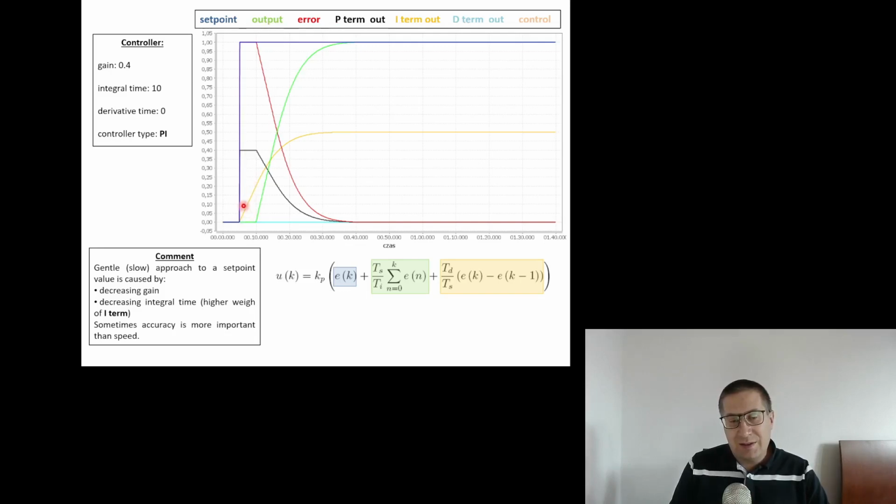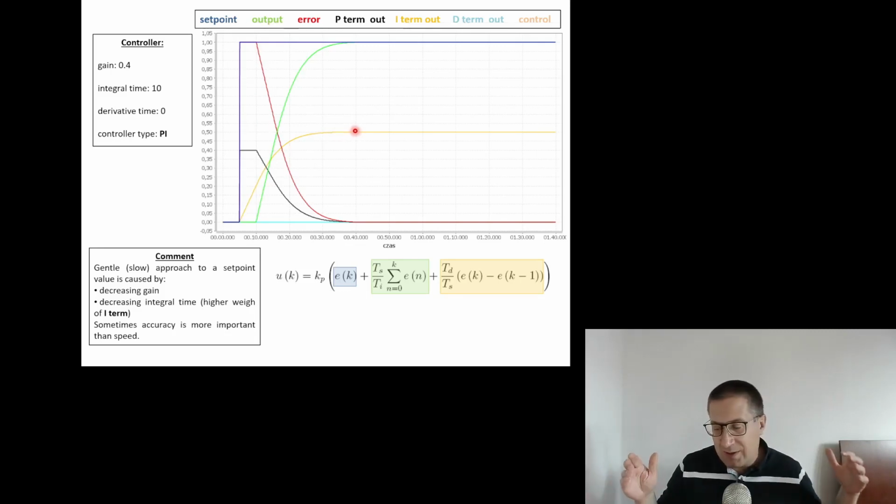If we see that the error is not moving, the error here is rising, we rely more on the past than on the current value of the error. So we have such a very smooth transition. We are reaching the set point without any bumps, any oscillations, right?